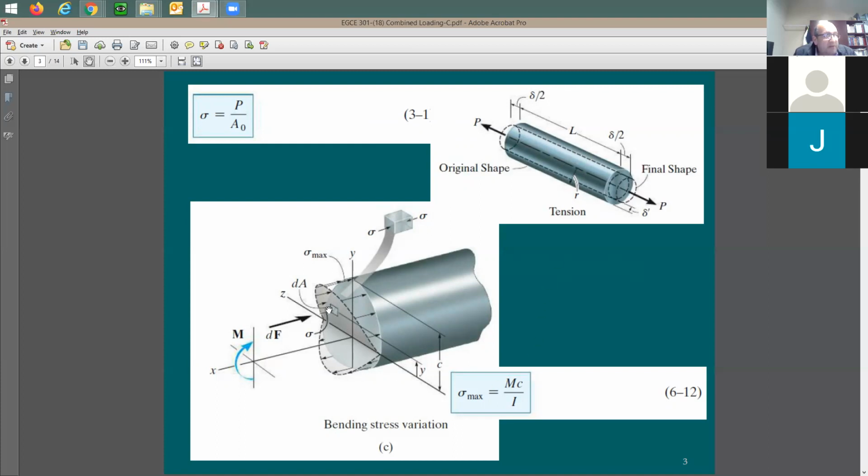When we have bending moment, we're going to have a combination. If the bending moment is like in this direction, we call this positive bending moment. What happens in positive bending moment? You're going to have tension on the bottom fibers, compression on the top fibers. This is also going to be creating compressive stresses. So it's going to be normal stresses top and bottom of the beam. But this is not due to an axial load. This is going to be due to some applied moment.